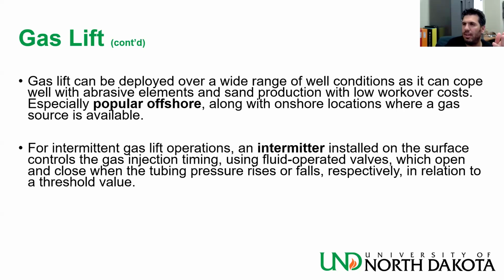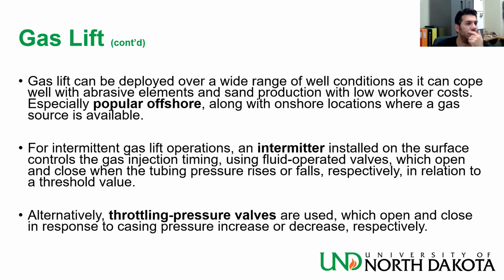And what determines how it gets activated sometimes is a pressure threshold. If they go above a certain pressure, they let fluid go in. If they go lower than a certain pressure, they let fluid go out, or it really depends. Or the opposite, actually. If the pressure drops below a certain level, they open, they allow you to inject. If it goes above a certain level, it stops you from injecting. You need to bleed off the existing pressure and then see how to move on.